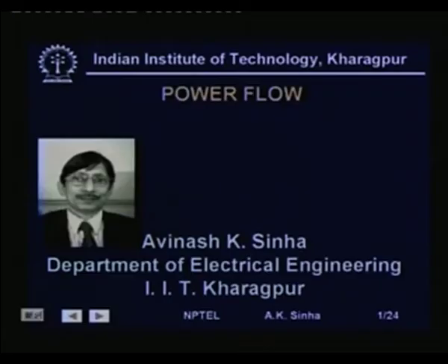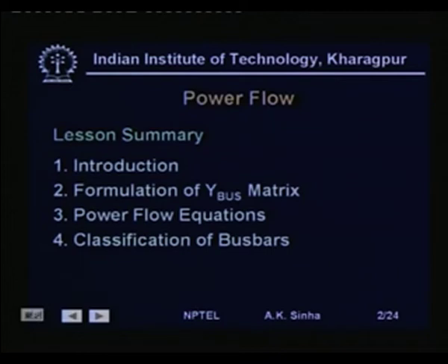Welcome to lesson 16 on power system analysis. In this lesson we will talk about the power flow problem. We will start with an introduction to the power flow problem, then we will talk about how we formulate the Y-bus matrix, then we will derive the power flow equations, and finally we will be talking about how we classify the bus bars into different types for power flow problem.